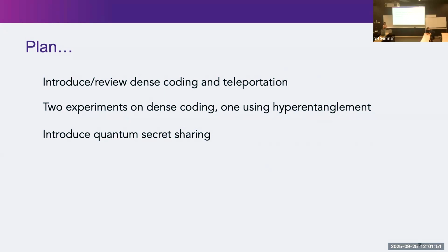So I was more interested about the reverse engineering. So if I understand, you just design the pattern and you print it as it is, and it worked perfectly the first try? Yes. So we define what is the function of the device. Okay, so say send TE0 to this port, send TE1 to this port. And then we give the algorithm a 3x3 area of silicon. It gives us this wild looking pattern, and we just go to the EBL and actually fabricate that.